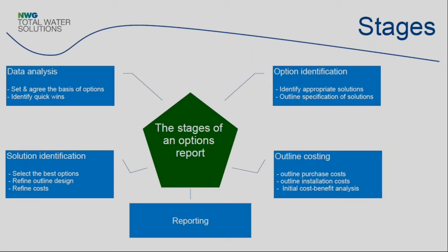So if we think of effluent treatment, that could be what's the maximum volume of effluent I need to treat? What's the composition of it? What are the regulatory concerns? Are there any timescales I need to meet? The other thing that could come out of that stage as well with data analysis is identifying any quick wins. So that might be, as you're going through the data, you might realise that actually there is something really quick I could do, which removes part of the problem. And that might then affect the level of investment and level of involvement that you need downstream in the programme. So data analysis is always the first part of this.